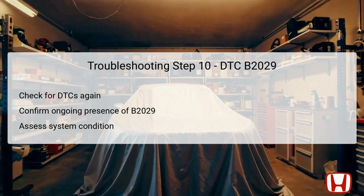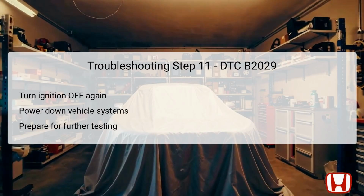In this next step of troubleshooting, the technician needs to turn the ignition switch to the lock position or again use the engine's start-stop button to select the off mode.